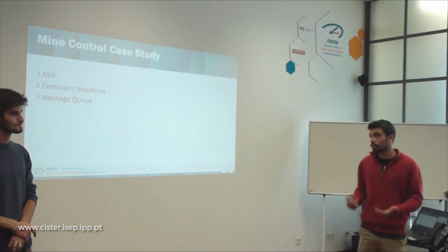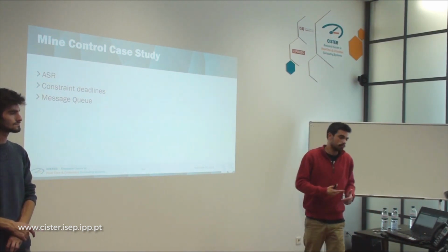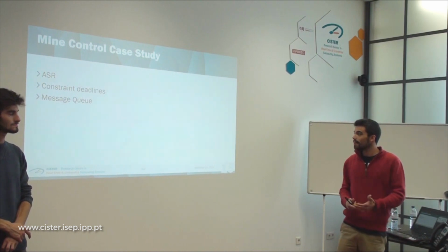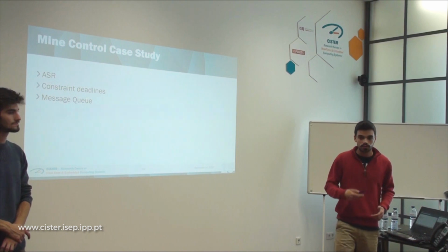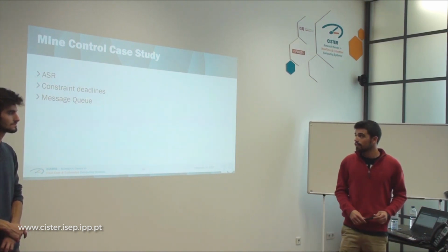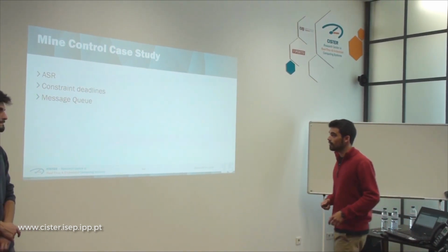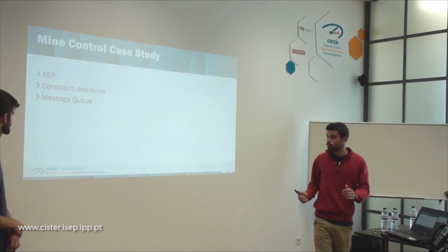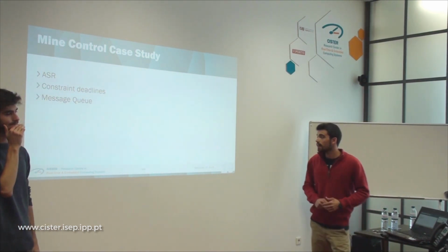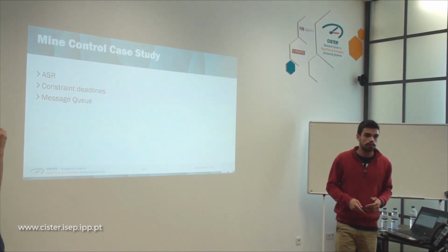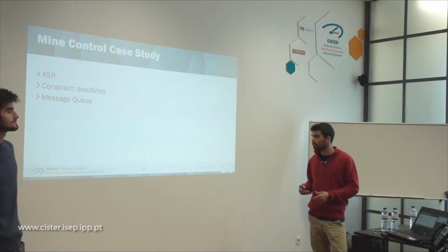Sadly for us, that was a problem, because we would lose a little bit of our critical situation to turn off the pump when the methane level is critical. So we had to turn around the use of asynchronous service routines, and we used states. Also, to send the alarms to the operator, we decided to use message queues that already offer us a little bit of synchronization, so we didn't have to worry about that.